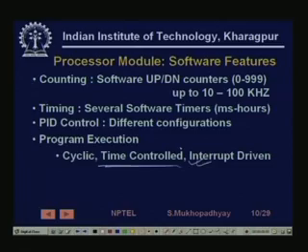There are some tasks which can suddenly occur, like failures kind of tasks, which once they occur are not taken into consideration in the regular computing flow, but once they occur they are required to have very high priority, and therefore they have to immediately get the attention of the processor. So such tasks are sometimes coded in the interrupt driven execution mode. So whatever the processor was doing, it will be interrupted, and this requirement will be catered to.